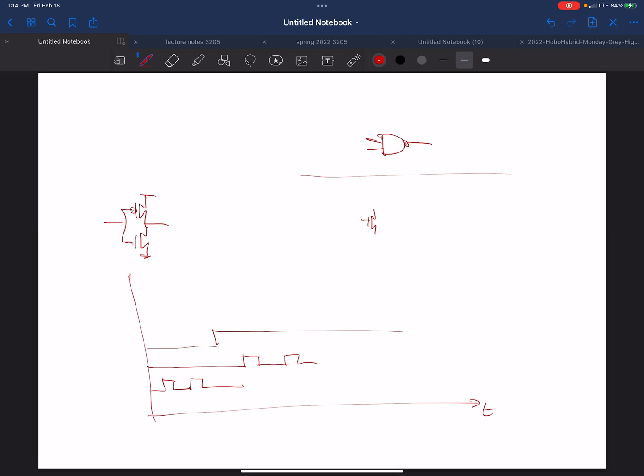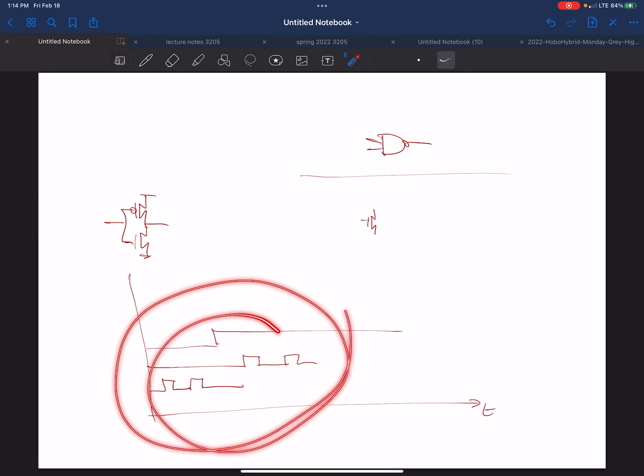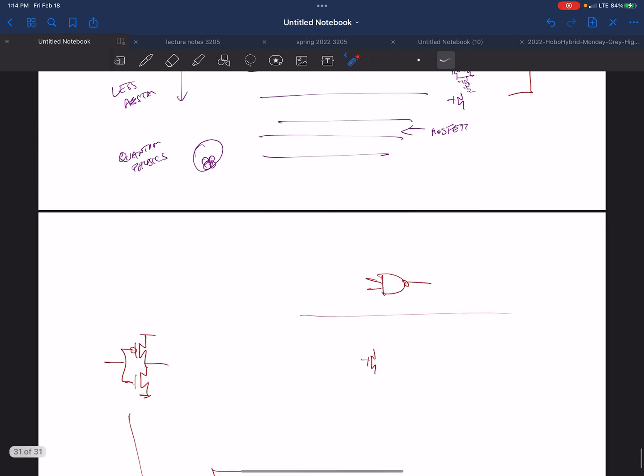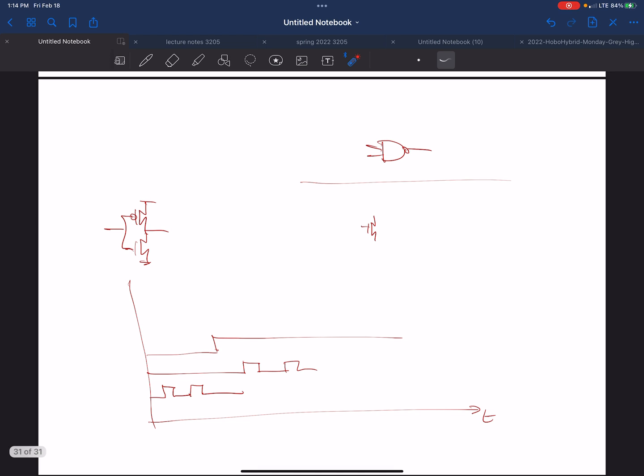What we're learning in this class is how to make stuff that does this, the real this. Because again, zeros and ones don't exist. Two different voltages exist, and we call one of them a 0 and the other a 1. And there are no perfect edges. Perfectly fast edges don't exist. There's some rise time, fall time, and that's what we see in the circuit.